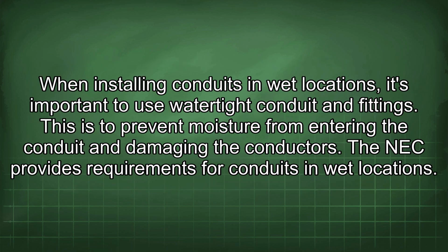When installing conduits in wet locations, it's important to use watertight conduit and fittings. This is to prevent moisture from entering the conduit and damaging the conductors. The NEC provides requirements for conduits in wet locations.